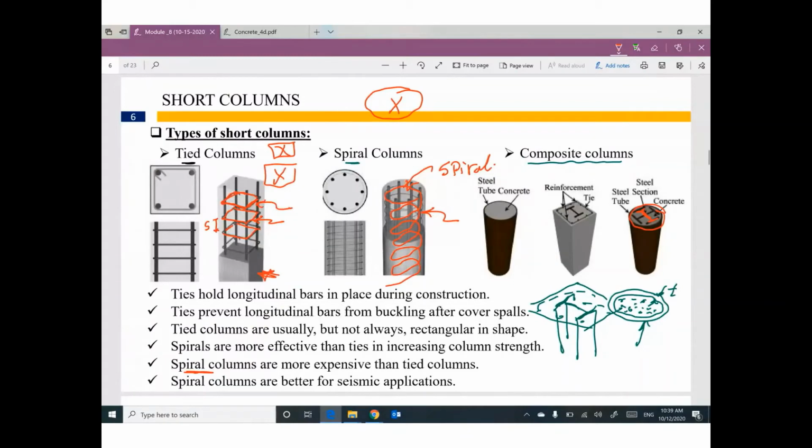Guys, we have here vertical reinforcement. These vertical reinforcements are very thin. I know they are inside concrete, but during application of a force, if you have a huge amount of vertical force, it can make this bar buckle. If this bar is alone, without any connection with the other bars, I can expect buckling.